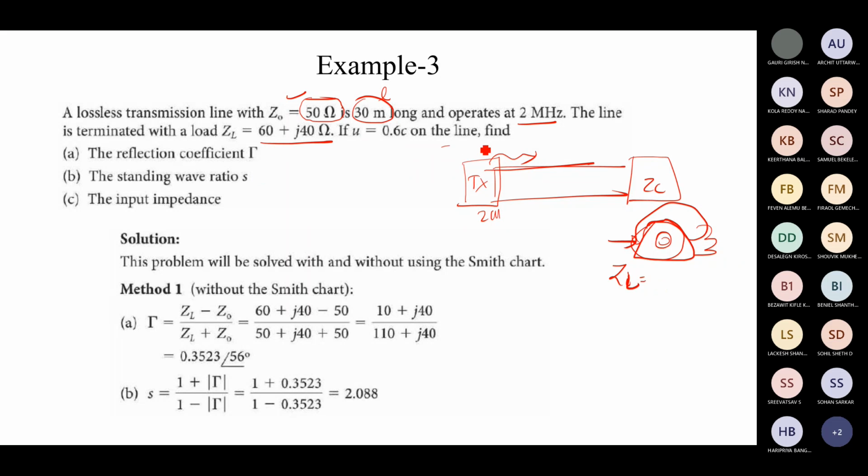Now what I have to do is, this telephone exchange is supposed to transmit the maximum power from here to here, and from here to here it is supposed to come back. This seems like a very simple problem, but it is very tricky, because it is supposed to be matched all the time. If the transmitter has ZS, the line has Z0, and the load has ZL, and they are not matched at all, what will happen? Whatever signal is supposed to come to us will be completely reflected back. Nothing will go to the receiver. We can't hear anything. You can even try that.